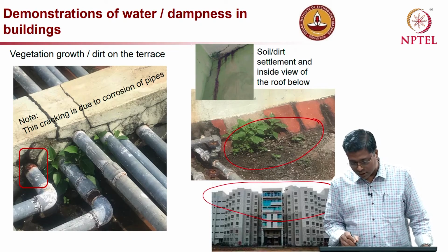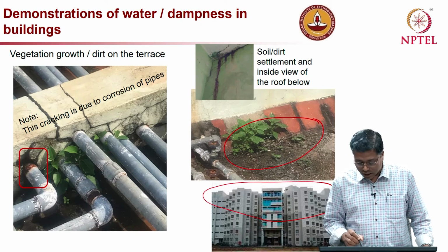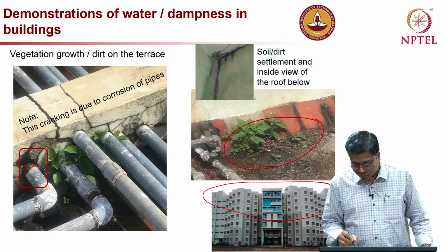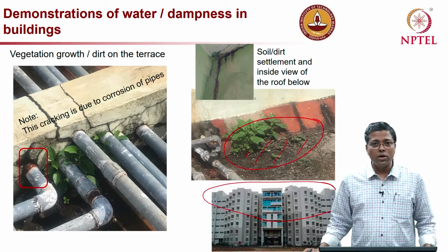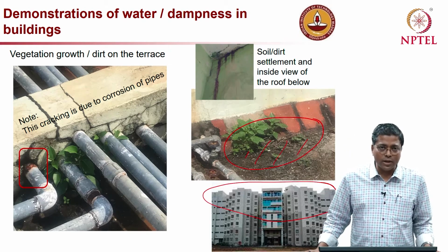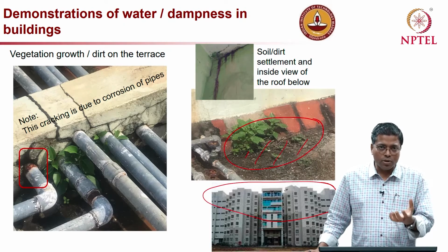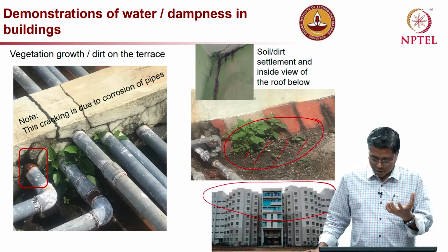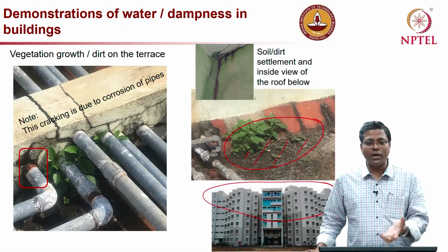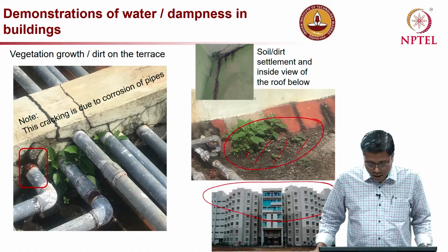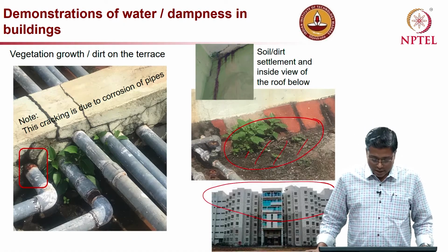And also you can see in this picture on the right side you have a lot of dirt accumulation. When you have soil there, that actually keeps the moisture, and then it keeps applying the moisture to the concrete below, which will eventually lead to cracking, etc.